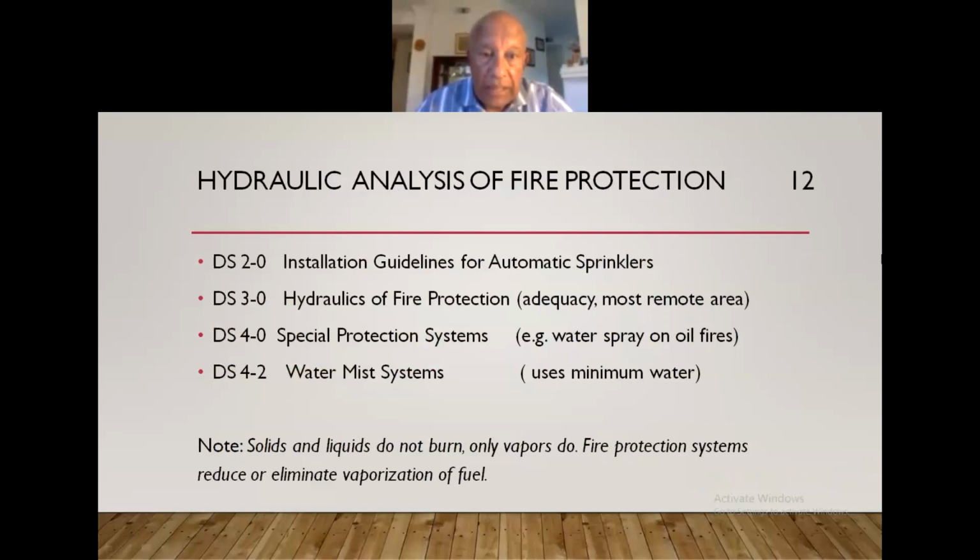So these are the standards that are based on the hydraulics laboratory, and it gives a theoretical background of doing network analysis of hydraulic systems. Fire protection is a hydraulic network analysis problem. So our engineers have to go into every factory and do a network analysis of their fire protection system, and make sure it can provide enough water to whatever is burning in the building. That's a complex process. It takes years of experience and a sophisticated computer program to do.